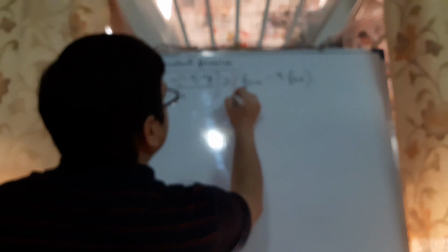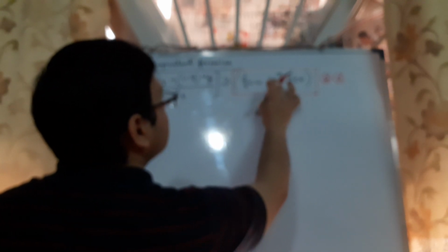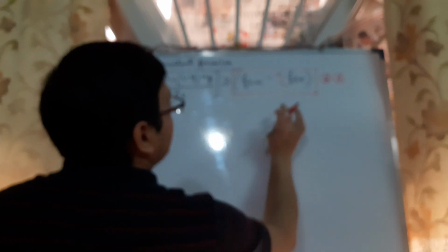So this portion, obviously both are important, but this portion of the formula is more important. That is FTR should be greater than or equals to FCW, that is the compressive force at the working load, minus eta FTT, the tensile force at the transfer.